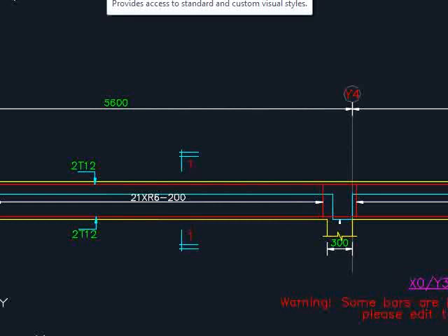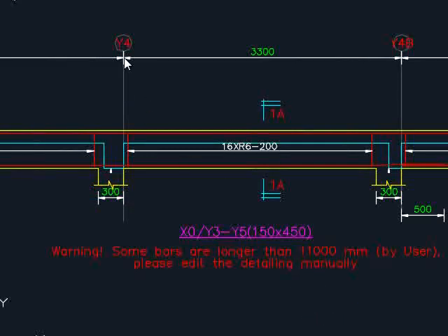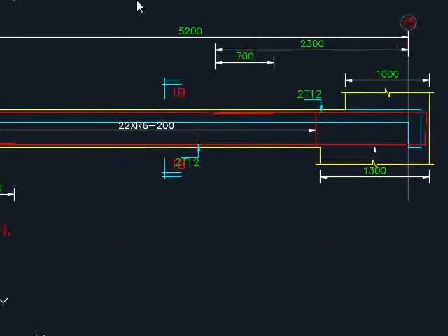You need to consider the mechanism of site inspections, where the site engineers or the consultant will need to check element by element. It will be good if you have all this clearly provided. Sometimes there are notes here indicating the possibility of the reinforcement bar exceeding the maximum allowable length, which is 12 meters. It is likely for you to have lapping of the reinforcement bar somewhere along the member. And sometimes you see overlaying of the text, which you need to modify.